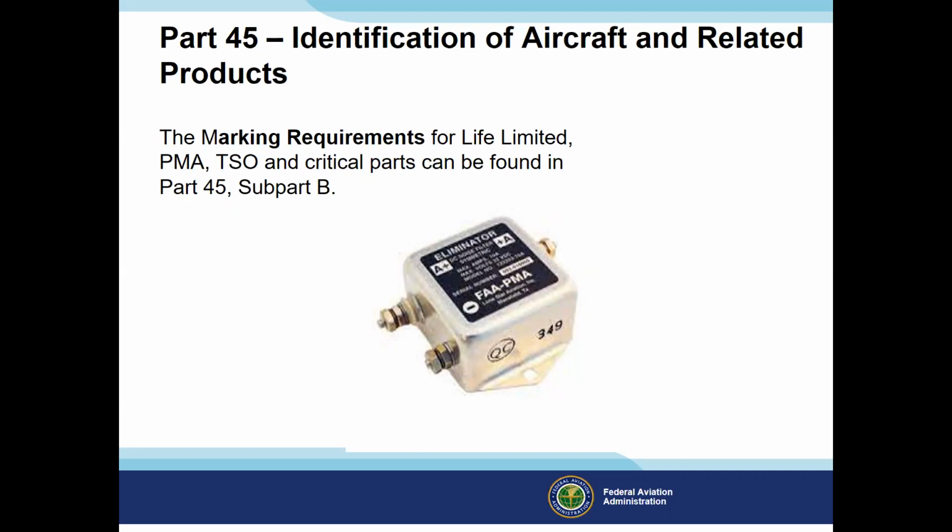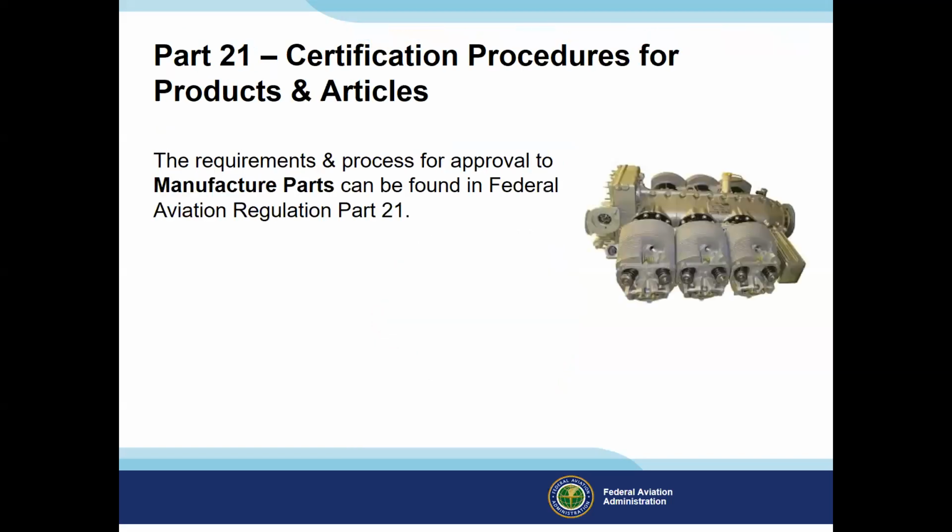And I just had Mr. Naylor ask, wouldn't a FAA 8130 form help clarify that the part is accepted? That is one of the forms, and absolutely, Mr. Naylor, that is one of the forms that is acceptable for use in determination of eligibility for a part in an aircraft or an engine or any other appliance, you name it. 8130s are our go-to. Most reputable manufacturers and even surplus part sellers have no problem issuing you an 8130 if you request it. Next slide, Gary.